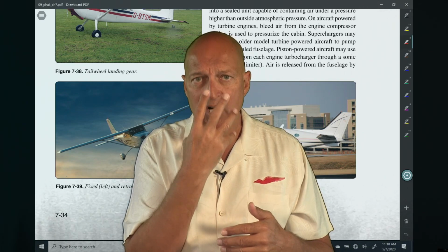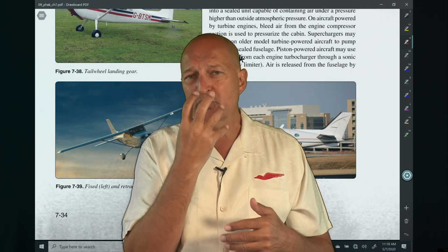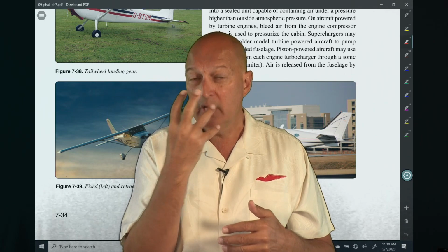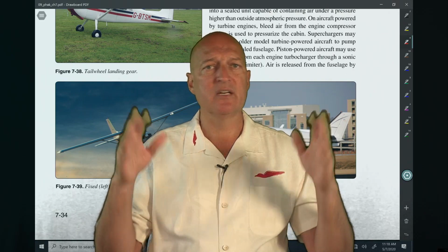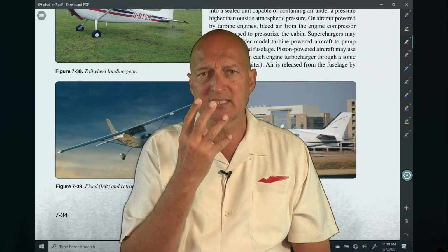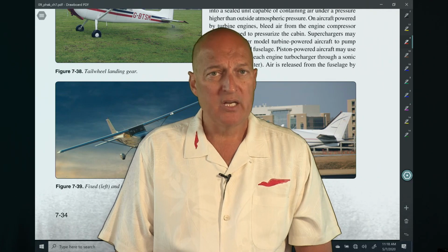So at about 17,000 feet, I actually have to put a mask on that gives me a better seal that can actually apply a little bit of pressure also, not quite like the big pressure masks like they use with fighter pilots, etc. But it's a similar type of concept, because once you get above 12,500 feet for a period of 30 minutes or more, you have to be on some form of supplemental oxygen in accordance with the regulations. And above 14,000 feet, you have to be on it anyway.